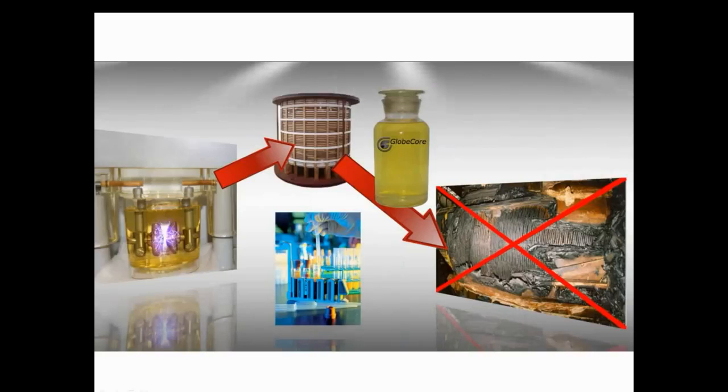Oil is well known through its 4 core functions, which are the following: dielectric strength provision, because oil acts as a dielectric and insulating medium; heat transfer, because oil is a cooling medium; solid insulation protection, which means oil is a barrier between the paper and damaging effects of oxygen and moisture; and diagnostic function, because oil is a perfect diagnostic tool to evaluate the true condition of a transformer inside, and especially the true condition of solid insulation.